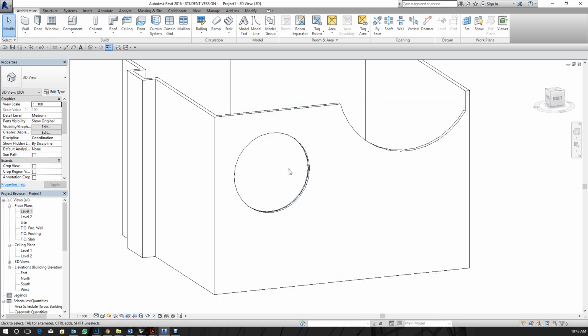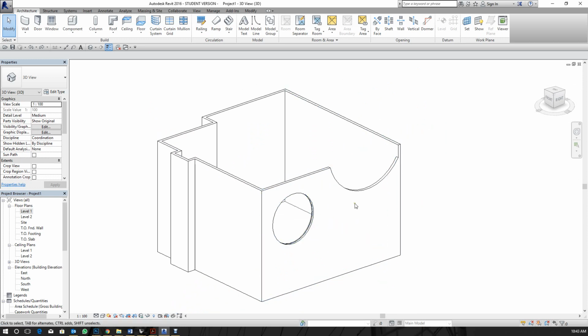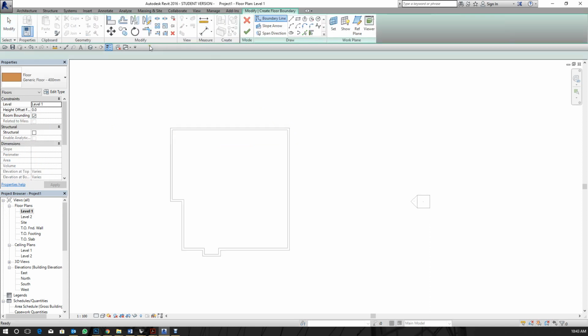Okay. Now if I was going to put a roof over this, and I was going to put some floors, I'll go back to my floor plan level, and let's start with the floor. With the floor, I can just click Architectural Floor. You'd really not need anything more than that, unless you get into practicing your modeling details for exchange between professions.